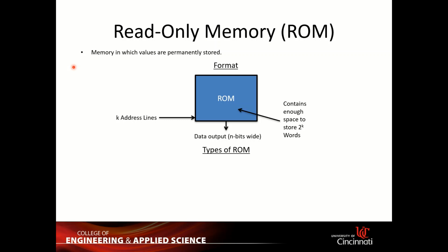This is costly. Just imagine it's like a tailor-made circuit. Every time you have a new circuit, a new design, you make a new mask, then you make a new device. So it costs a lot. Technically, this is not the most cost-effective way to do design. So fabricated ROM is not very cheap. So what is the other way?